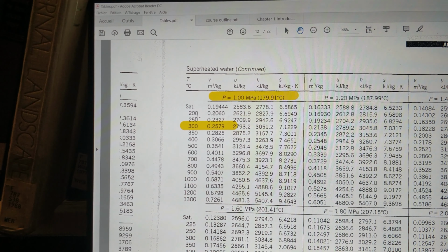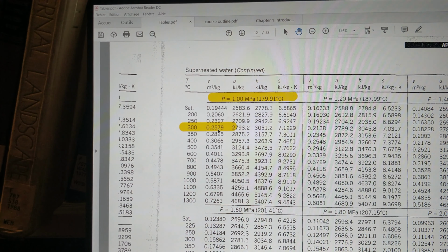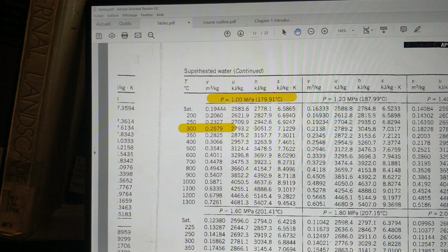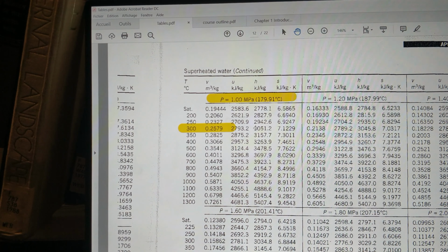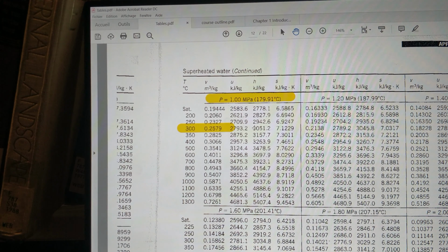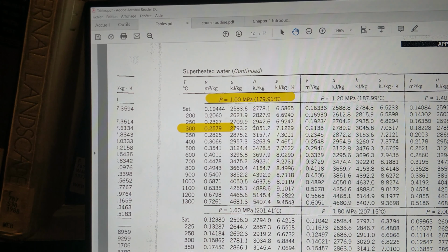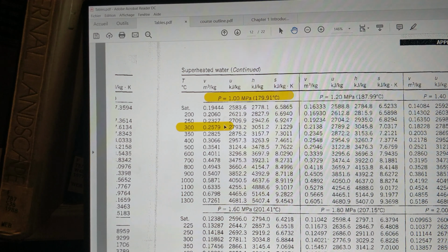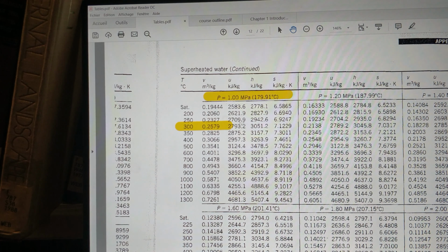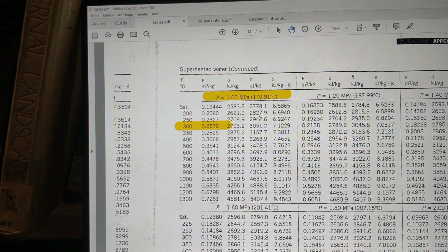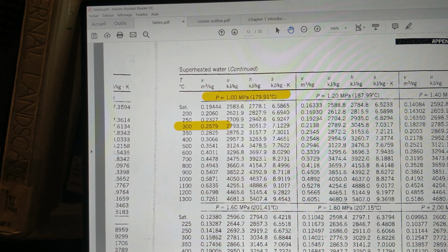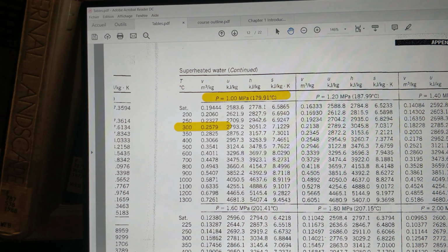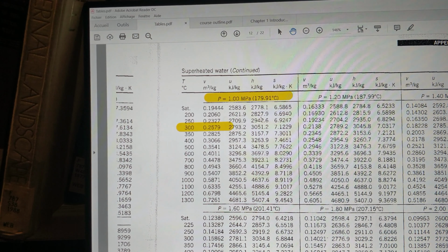We would pick two temperature values in our temperature column, and we would also pick two specific volume values, set them in our table, and add in that table our missing components, and thus create an equation with that table. Solving for the specific volume would equate to finding our solution to our problem.